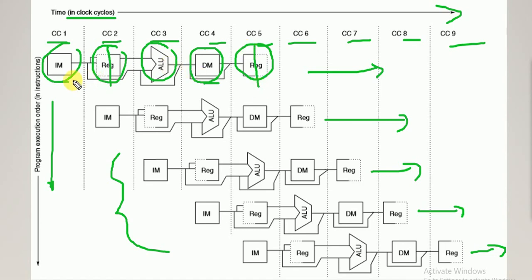For memory there is no conflict because we have separate caches, one for instruction memory and one for data memory. But for registers we do not have different register files, we have only one register file which is common. So for reading and writing we divide the same clock cycle into two halves, and perform read and write accordingly. I hope it is clear.